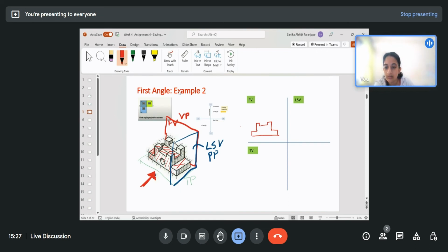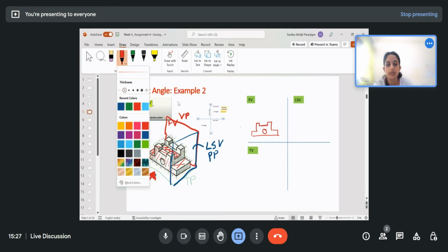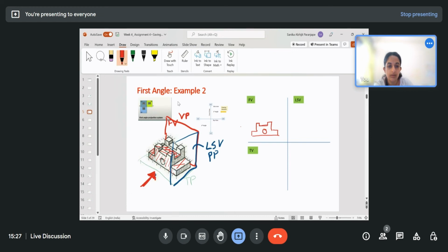And we'll be able to see this hole exactly as a circle over here. And then just below this line, we'll be able to see this particular horizontal plane as a hidden line, like this. And all these are in line with this one, this is in line with this one. So these objects won't be separately visible in the front view.